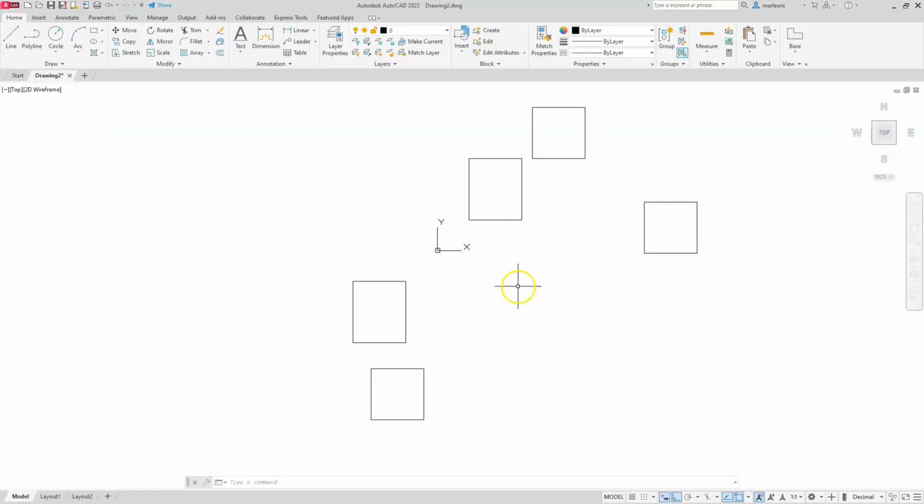Okay, so starting with this one, let's put some values in here and create some lines. I'm going to start a line, and remember I can absolutely tell it where the first point is, or I can click somewhere on the screen, or we're going to click on O snaps when we start discussing that. So I'm going to click here, and now it's asking me which direction is my next point. I have my dynamic input on. You can see on my screen that it's graphically next to my cursor. So I'm going to type in 5.